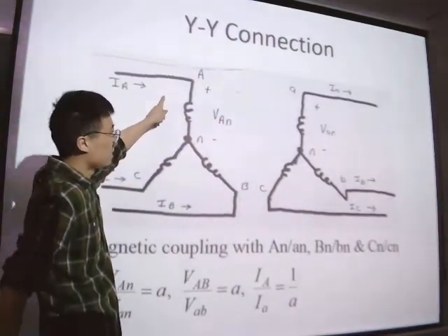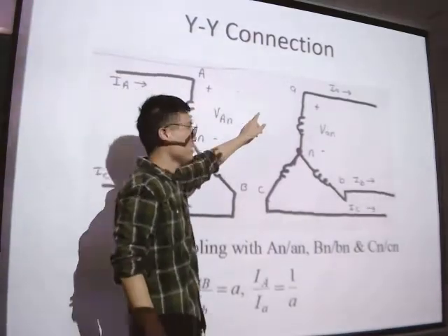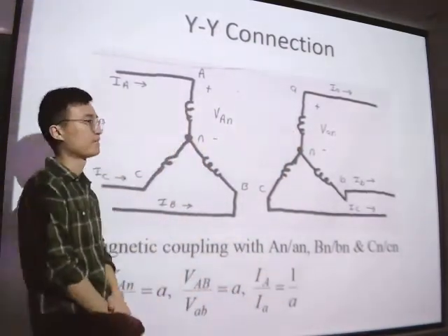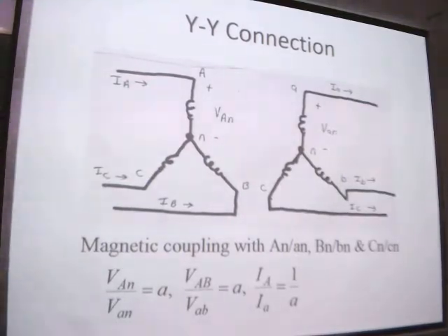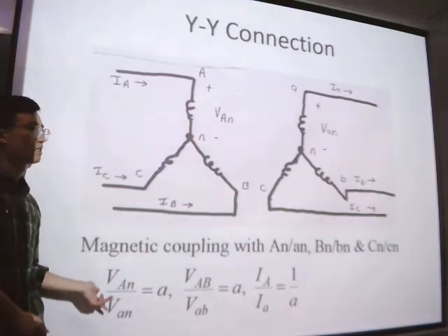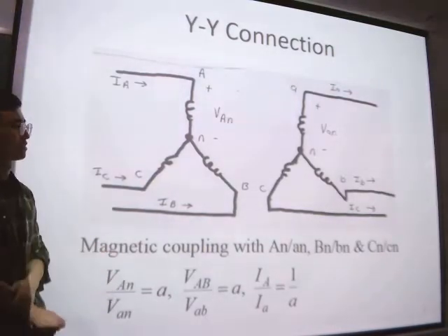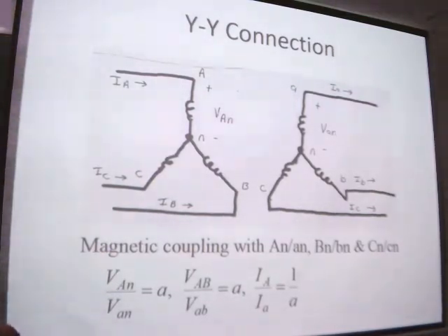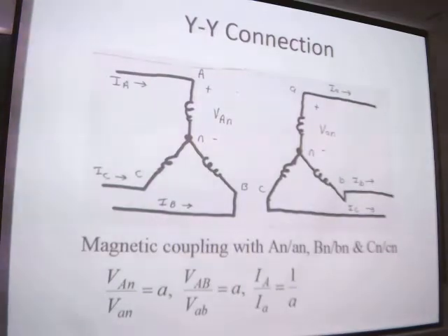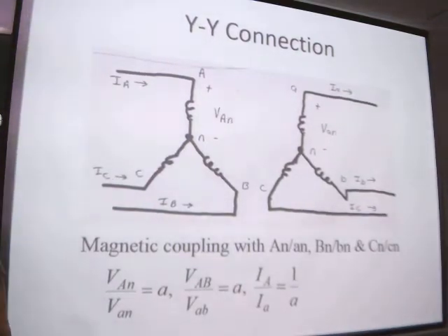So the current on the primary side to the secondary side is also 1 divided by a. So you see the Y connection should have exactly the same definition as the single phase transformers. Okay, so it's the simplest, the Y connection.